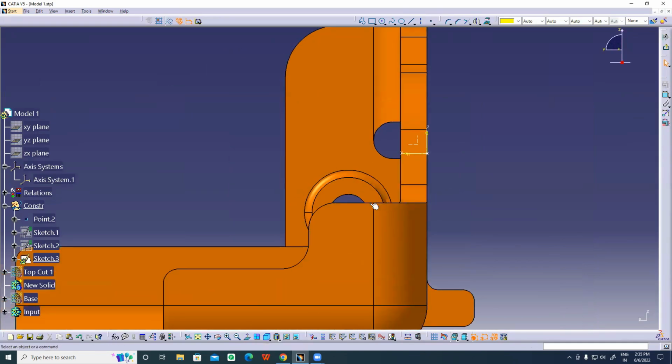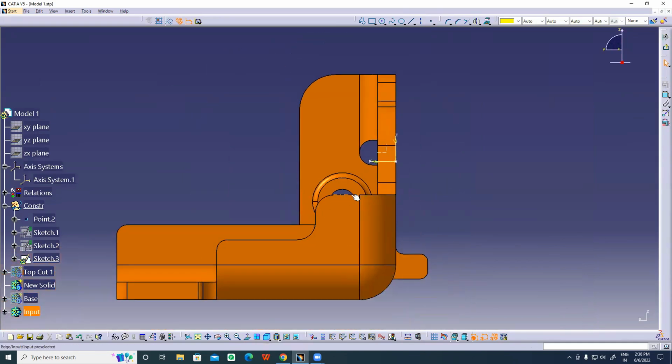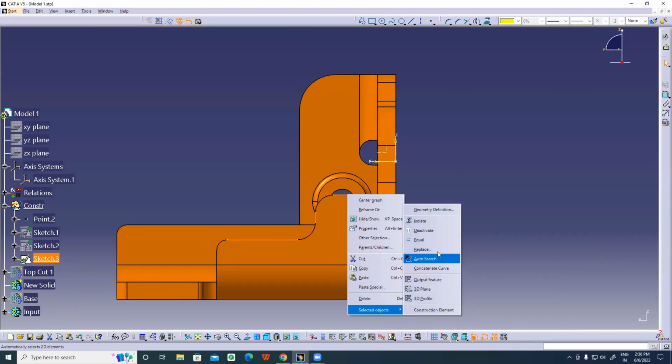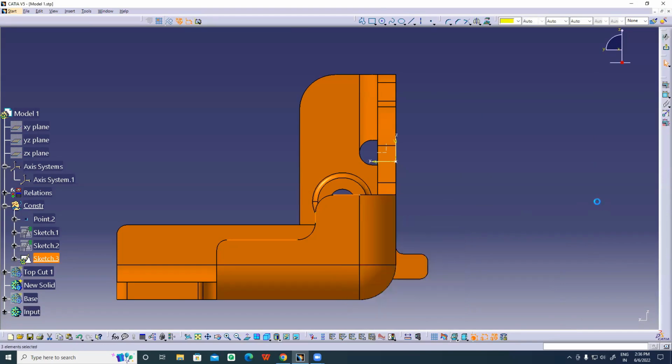Okay. Now what I'll be doing is, this is a straight line, and you can see there is a straight line available in this portion. And lastly, this is a straight line. Selecting all three, projecting this, right click and isolate it. Once I isolate it, go to a normal trim, this and this, and extend the length of this slightly, and extend the length of this also slightly. Once after that, I'm going to a dimension.